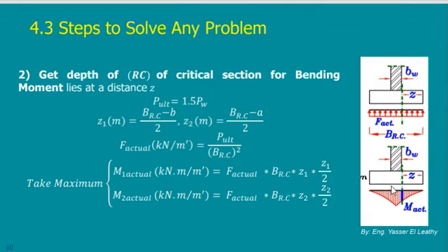Here for calculating the bending moment, we said that we are not going to calculate the bending moment till the center line of the column. Why? Just to make some reduction in the cost, because I can calculate the moment just on the edge of the column, because actually this is the critical section. Once I go inside the column, it's another section.